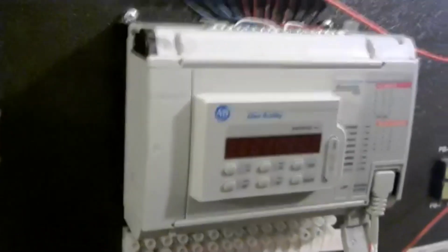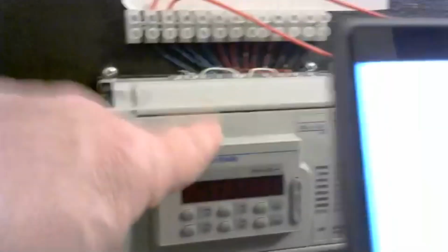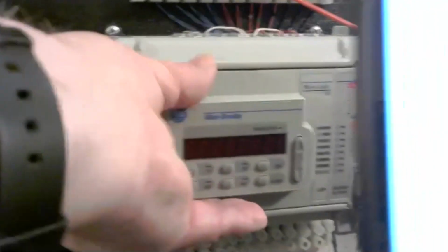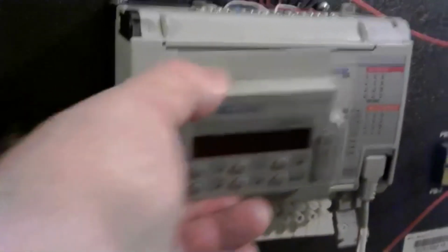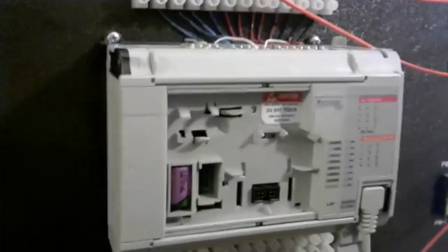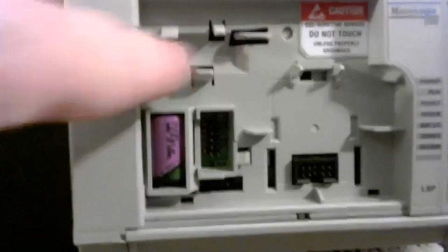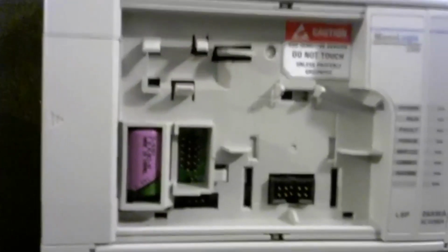Everybody good with that? Yes, sir. Also, the front of this pulls off too. You can grip the front and wiggle it carefully, and the front comes off. There's a permanent lithium battery in there that's soldered in. You can't take it out. And then there's a place in here for another one. If this thing is going to have power out for a long period of time, you buy a lithium battery with a pigtail, snap it into here, and then plug it into a connector.